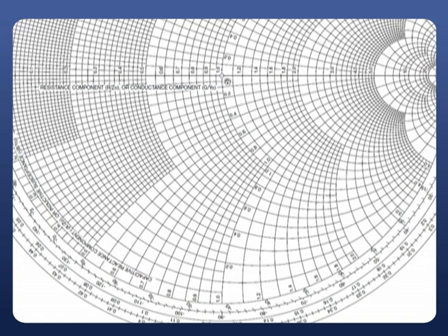Now while you are moving from the center point to the point of open circuit along this line, clearly observe the line that I am showing. Along this line the voltage is always maximum. As this particular point is the open circuit point, you will always get the maximum voltage, right? So clearly it's from the center point of the Smith chart to the extreme right point, that is nothing but our point of open circuit. Whenever we observe this line, it is said to be the maximum voltage line or minimum current line.